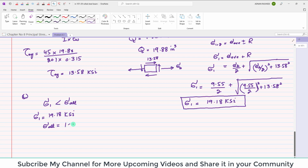So you can see your principal stress here for safe specification. Clear? But you can see from the value that sigma 1 is greater than sigma allowable. Clear? Hence, what we conclude is that W10 by 39 is not acceptable.